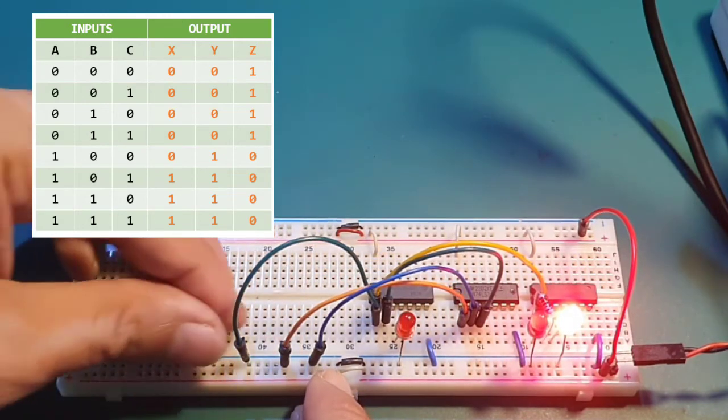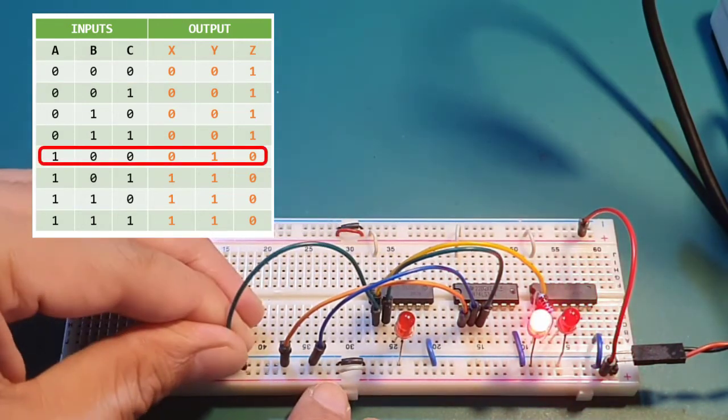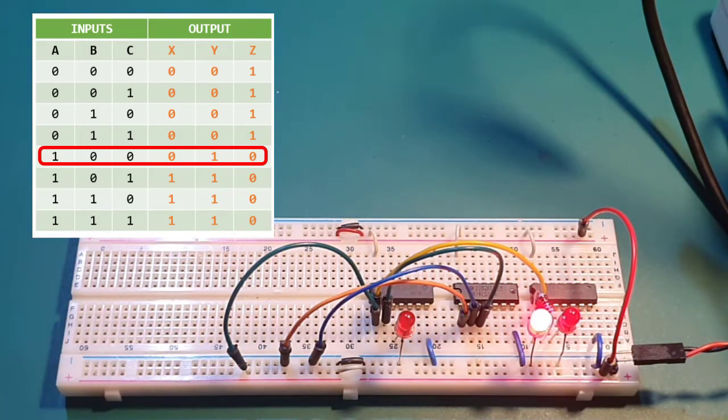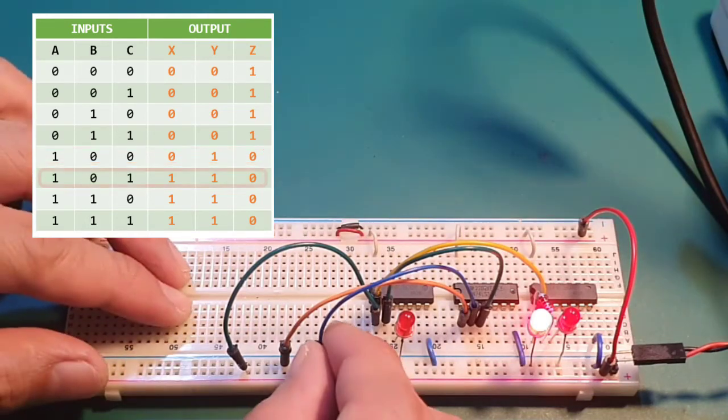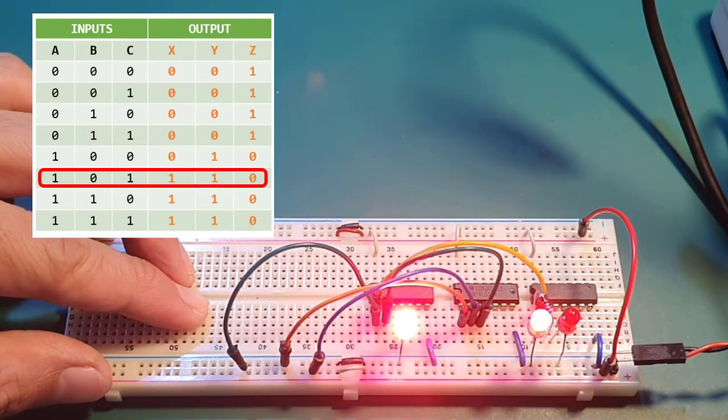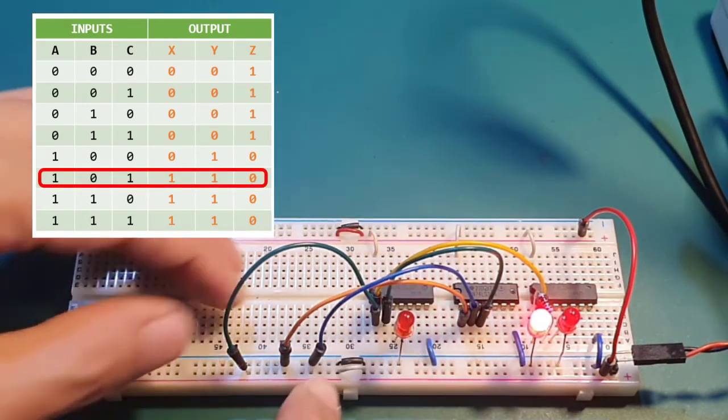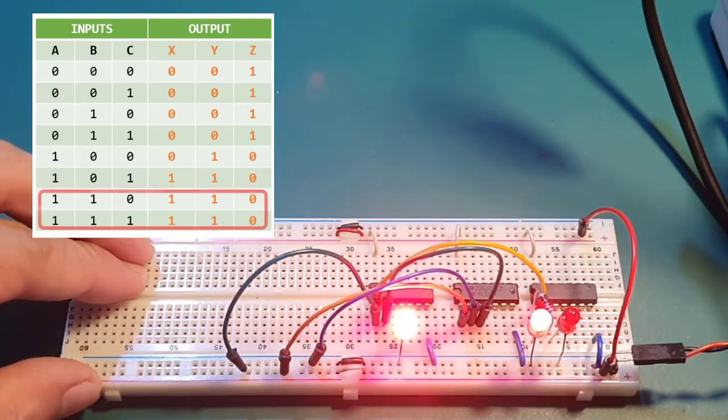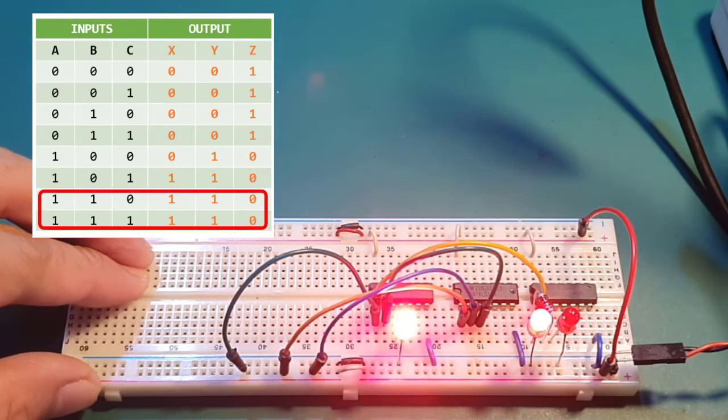And now, at 1, 0, 0, the main switch is activated and the outputs Y and Z invert their signals based on our truth table. This simulates the locking of the door. However, the light bulb is still off, and it will only turn on if one of the light sensors from inputs B and C detects dark surroundings. At input 1, 0, 1, the light bulb turns on, as well as at input conditions of 1, 1, 0 and at 1, 1, 1.